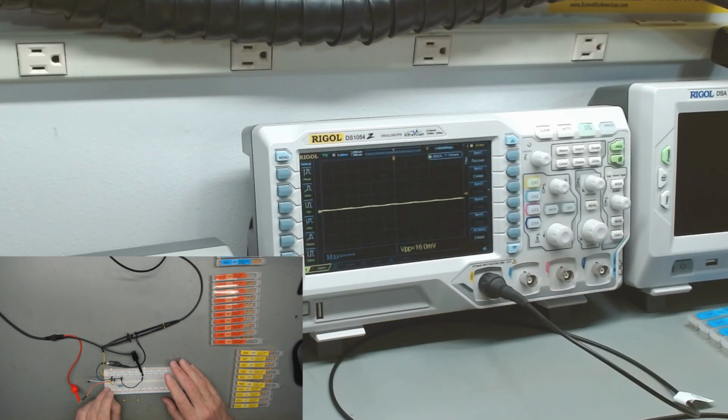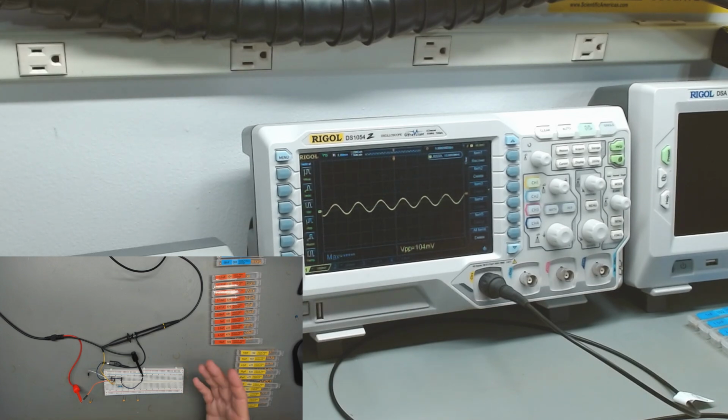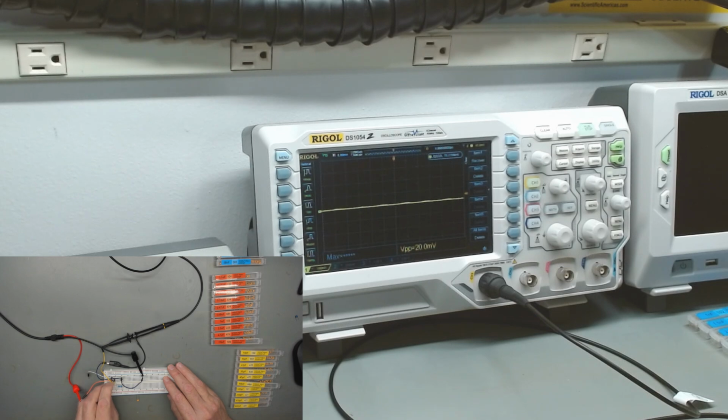I'm going to move down now to a 68 picofarad, and let's look at what happens. Okay, now I'm down to around 100 millivolts. So we've had a dramatic loss. The insertion loss has come up. We've got a much higher loss in our signal. So let's move from our 68 to our 33, and progressively this should get worse as we go. Okay, now we're down to about 56 millivolts, as you can see. So each time we go down in capacitance, our signal is being restricted more. So here is our 10 picofarad, and you can see we're only barely 24, 28 millivolts. We barely got a signal anymore.